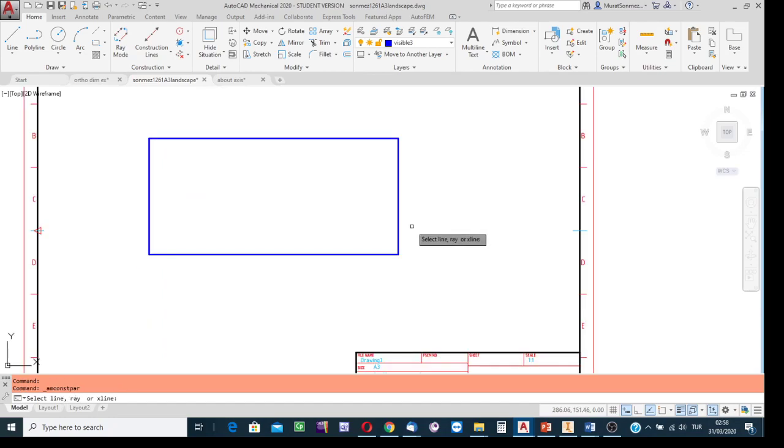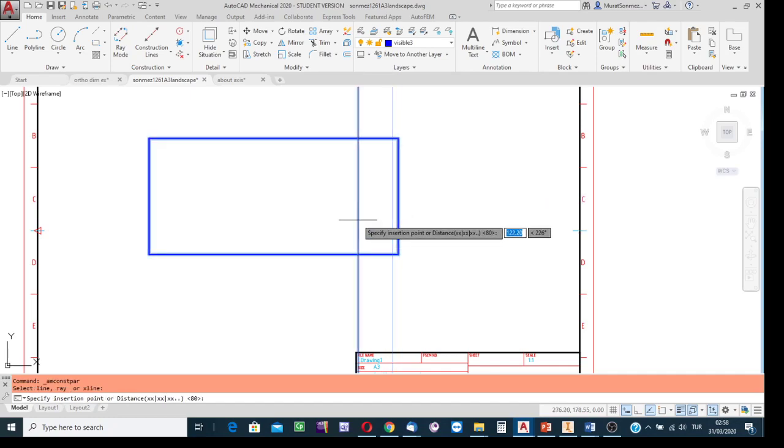As the reference for the transfer line, it is to be a certain number of millimeters away. In this example, this line, which corresponds to the view of the right side surface, is the reference. With a click, indicate it, and then into the box along the train, it will be highlighted. Write the distance from that reference to the starting point of the chain line.